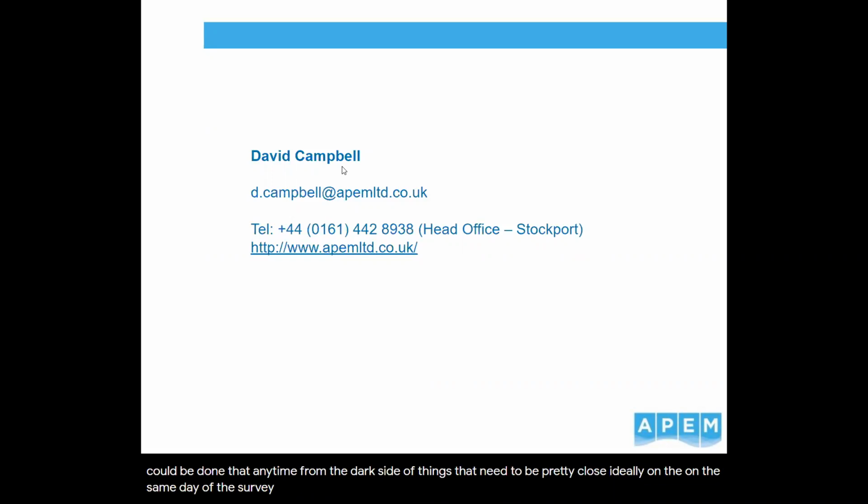So you would go to a point on the river and collect that depth calibration data on the day or very close to it. Essentially, once conditions within the river change, that calibration data is not going to be valid. However, if we're moving on and deriving that photogrammetrically now, then that calibration data can be collected at any point.